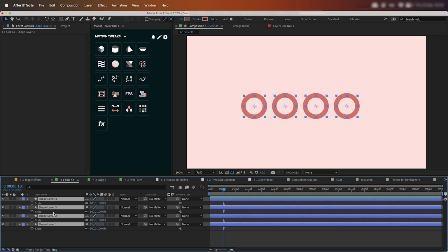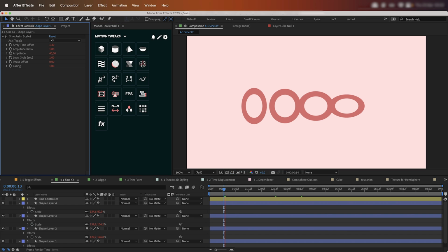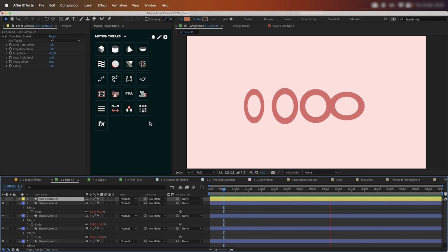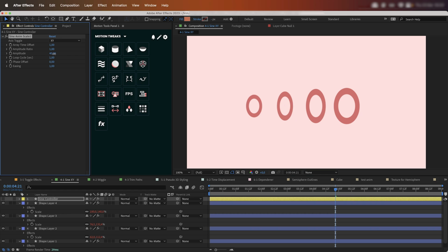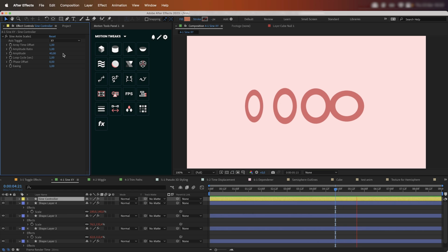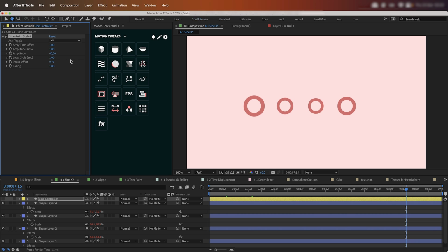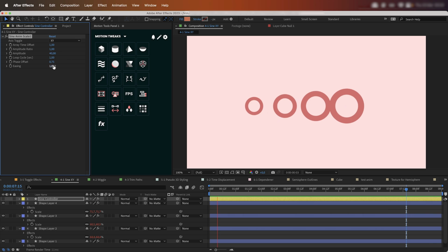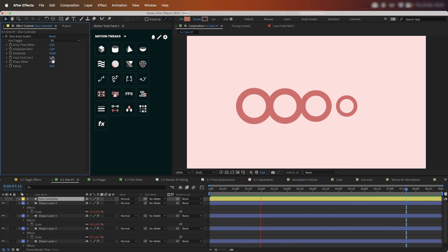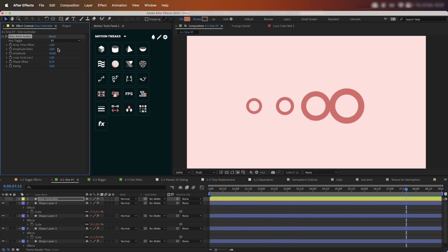This animation works on almost any property. You can try it on scale. As a result, the layers will be sequentially deformed along different axes. It may not be obvious at first that you can make the animation of two axes synchronous by adjusting phase offset. In this case, a value of 0.75 will work. By adjusting different parameters, you'll get very interesting results. That's all here. Let's move on.